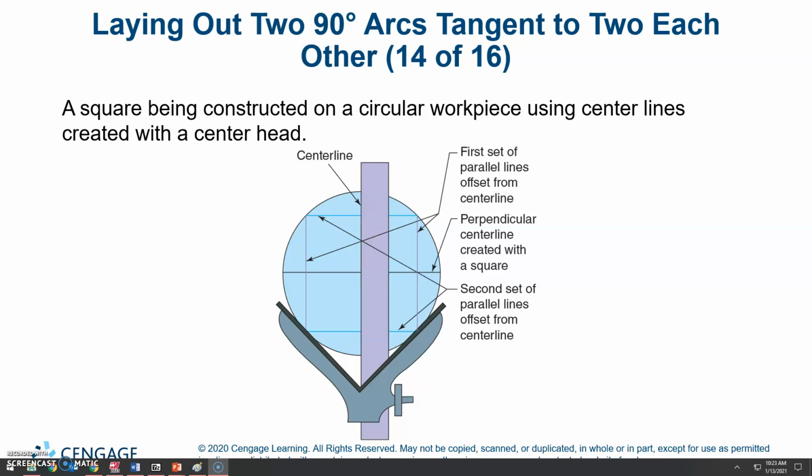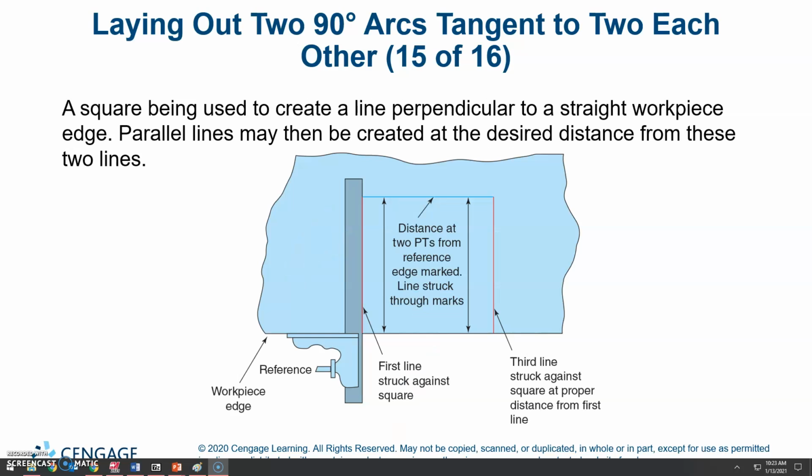A square being constructed on a circular workpiece using center lines created with a center head. First set of parallel lines offset from the center line. Perpendicular center line created with a square. And second set of parallel lines offset from the center line.